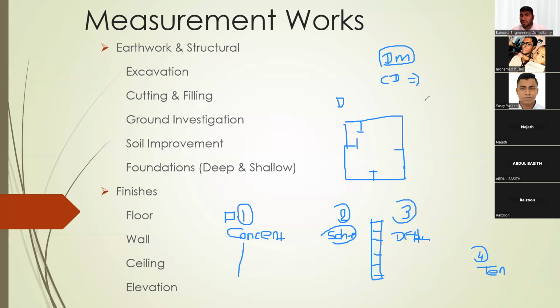Civil defense always looks at the safety of the building, whether this building is designed in a way that is safe for people to live in. This is the duty of civil defense to check. So what will they check in terms of fire? The doors, where there is a fire, places that can be easily accessed need to be fire rated. It can be the lobby and the lobby door, and all this information they will check for safety. Can this wall catch fire or not? They will also check the sprinkler system and the external facade system. They also check the ceiling height, and how much height is above the ceiling to the slab. If it is more than 1 meter or 1.5 meters, you need to put another sprinkler on top of it. So there are so many regulations.